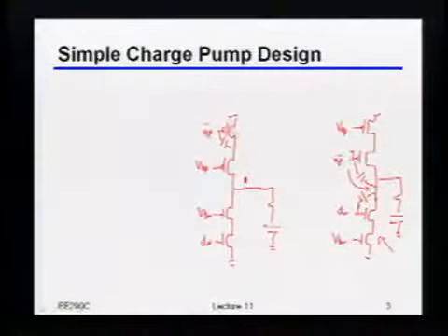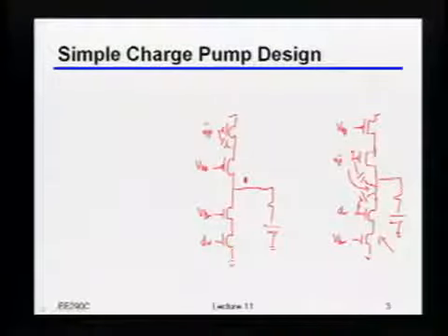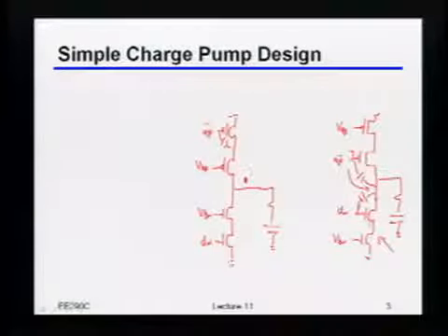What might be a little bit different if I build things this way versus this way? And remember, those switches are turning on and off fairly often. The VGS keeps changing? Between what and what? Between the two cases. Yeah, okay, so you're saying here we're changing the VGS of the current source device, whereas here we're changing just the VGS of the switch. That is true, although I don't think there's really a way around that because we have to turn things on and off. So somewhere something like a VGS is going to have to change.